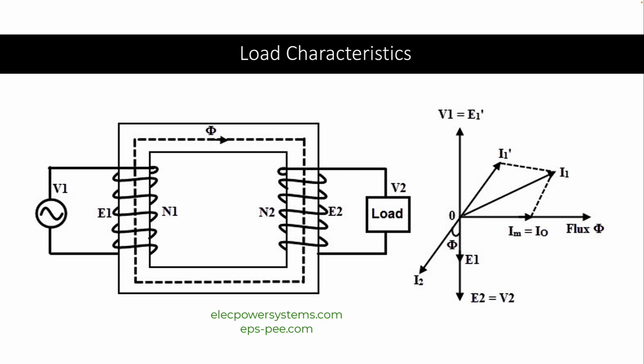The total current in the primary circuit is the phasor sum of the primary load current and the no-load exciting current. The no-load exciting current represents the magnetizing current and the core loss component, while the primary load current accounts for the current required to balance the secondary load current. By balancing the load currents on both sides of the transformer, the core remains in its initial magnetization state.